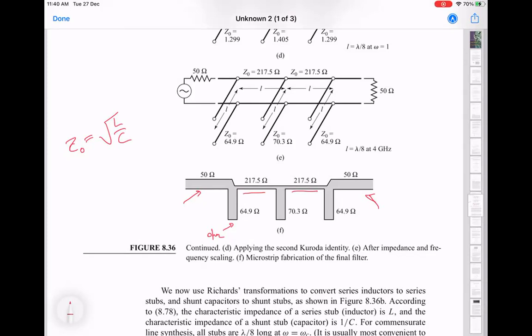Now, this is also not a perfect solution because as you go to high capacitance per unit length, the velocity of propagation also slows down, which means the wavelength also becomes smaller. So what is considered small also changes, right? So it's not a simple compromise, but it is possible to make maybe a 10 ohm transmission line if you really like.